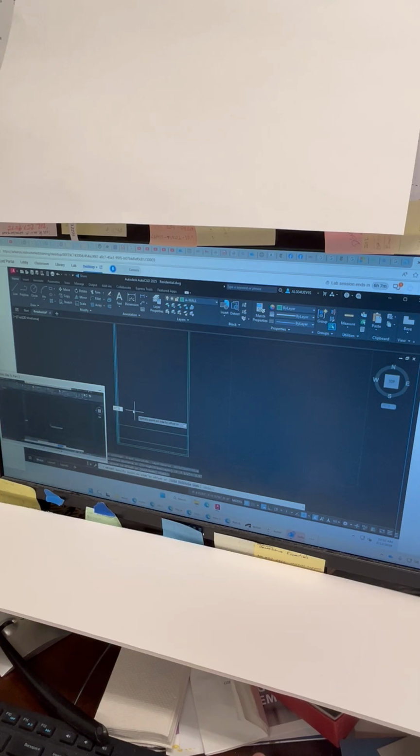The first dimension I want you to plug in is 3 foot 7.5. Anytime you enter a dimension into that text box, you're going to hit enter on your keyboard. Pretty soon I'm going to stop saying that, but I want to drill it into your head. You have to know when to hit enter and know when to pick. Know when to hold them and know when to fold them. All right, go ahead and hit enter.